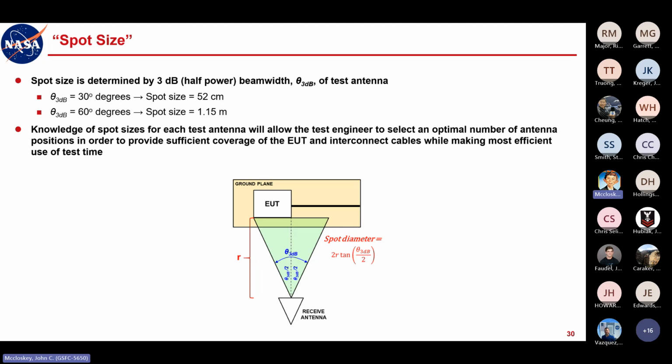For RE102, since the scans are generally pretty quick, if it's not real clear whether a given number of antenna positions is enough, just adding another antenna position is going to add an incremental amount of test time that is probably going to be in the noise, as it were. So for RE102, erring on the side of one more antenna position is generally not a big deal.